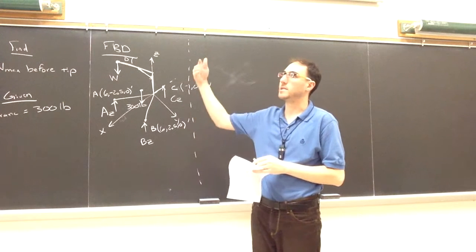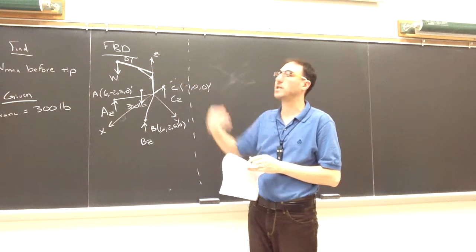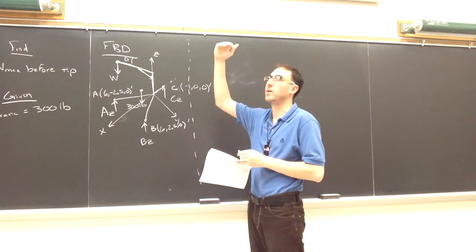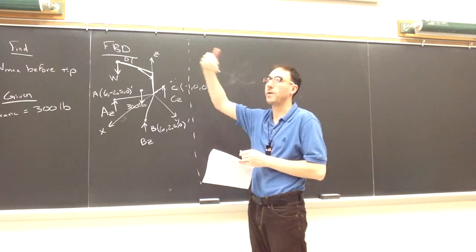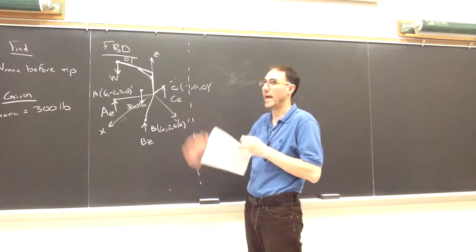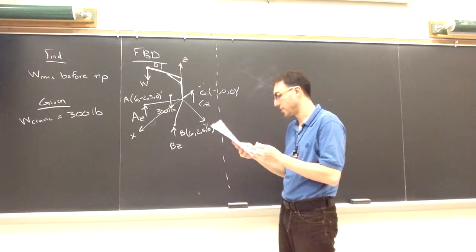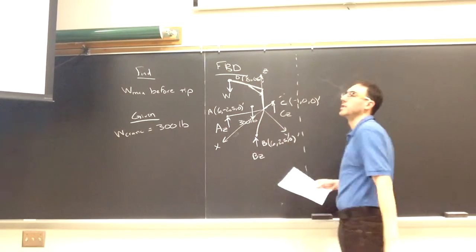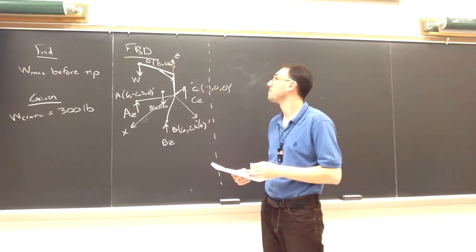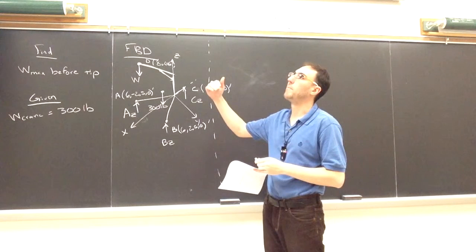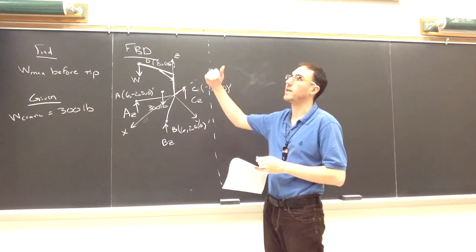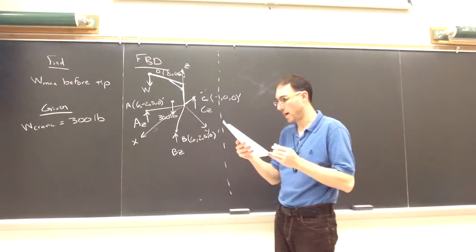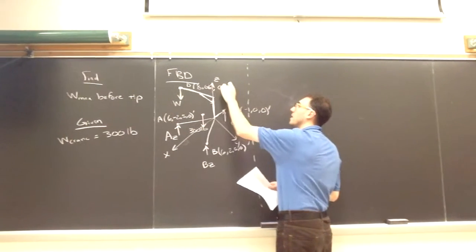degrees. That top boom arm is only in the X direction. So I'm only going to put its coordinates here, but we have to go up the Z. We'll go up a little bit from the 30 degrees, and we'll go in the positive X also due to that 30-degree angle. So if we actually do those calculations, we get in the X direction 8.66 feet. That's really just the 10 feet times cosine 30. And the Z direction, we go up by 1.5 feet, then another 3 feet, and then we go up by 10 sine 30 for a total height of 9.5 in the Z.